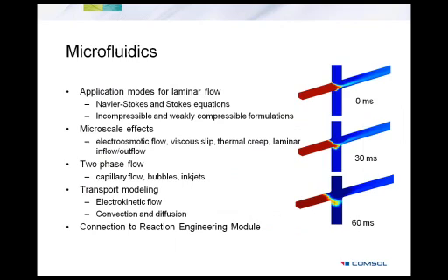There are some special interfaces and boundary conditions to deal with fluid flow, especially in the microscale. You can solve for laminar flow, which is basically incompressible Navier-Stokes, and you can also solve just Stokes flow equations if you wanted to. Stokes flow, for those who do not know, is very similar to the Navier-Stokes equations, except that the inertial term goes to 0 here. And these are suitable mainly for flows with very low Reynolds numbers.